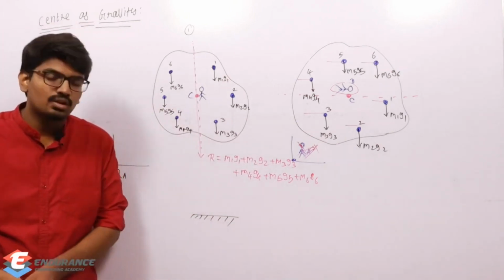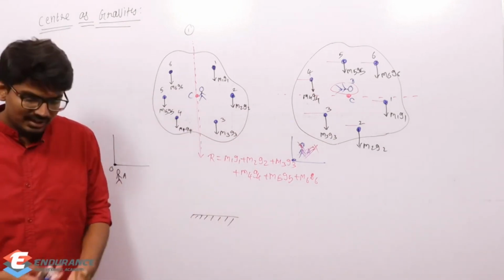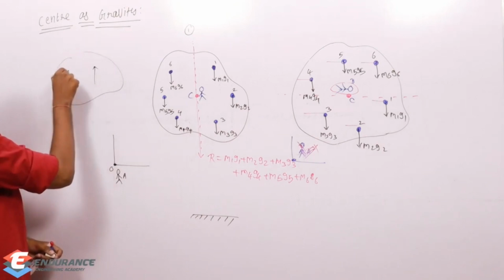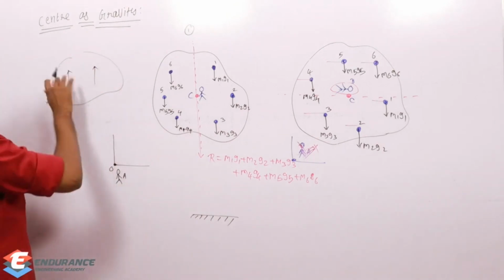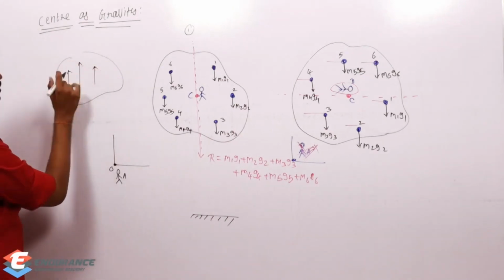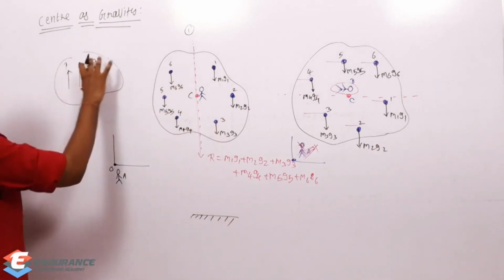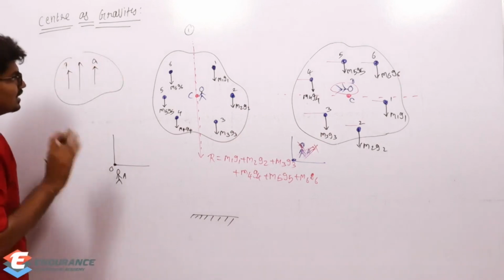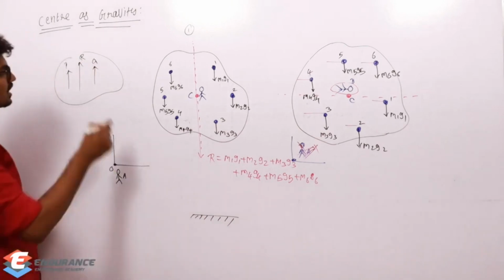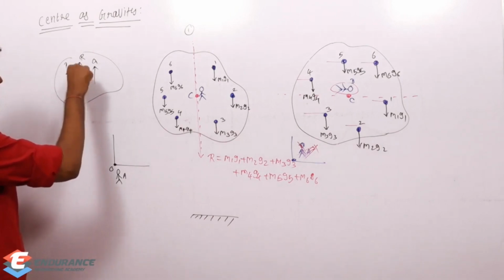If you have understood center of parallel forces properly, you can easily answer. What is center of parallel force saying? Whatever number of forces you take, I will be getting some resultant, right? If you change the orientation of two forces, P and Q, I'm just showing you an example with two forces, then this resultant will also change its orientation, but it always passes through only one point. That point is the center of parallel forces.